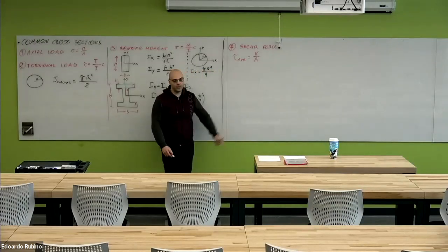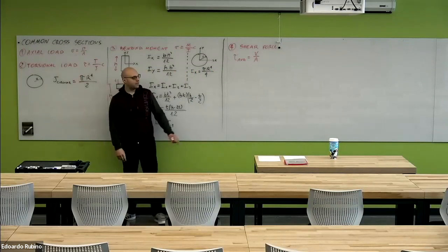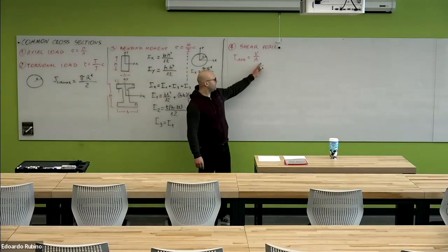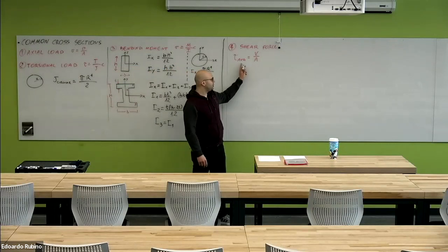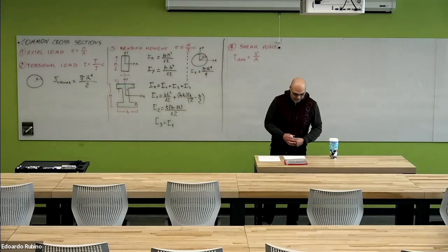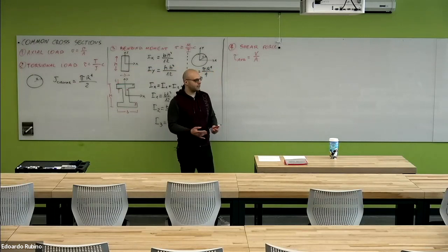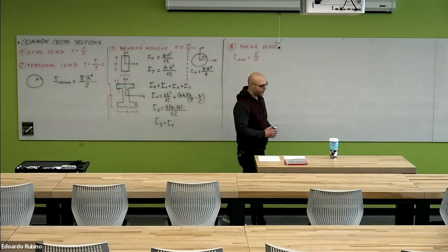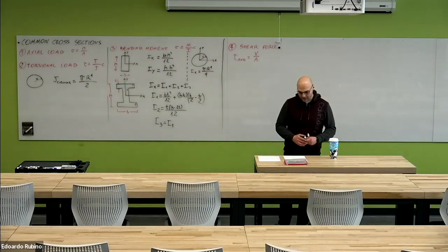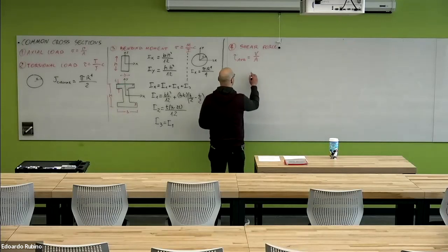So this equation here would be actually analogous to this equation here. But again, remember that this gives only an average of the shear stress on a certain cross section. If we want to look at how to apply the shear formula for a certain cross section, one cross section we can analyze is certainly a circular cross section.